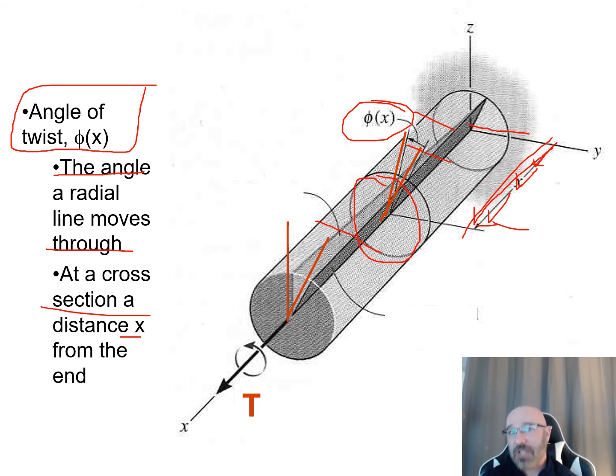So as we change that grid sensitivity, as we're talking about our mesh, as we're going into finite element analysis in a different program like MATLAB or something like that. If we're doing it by hand, we might just say, hey, okay, we looked at it at a centimeter away, we looked at it at 2 centimeters, 3 centimeters, whatever it is from our end distance over here, and we get down here and we see, okay, for that applied torque, once we get past 2 centimeters, we don't see much.